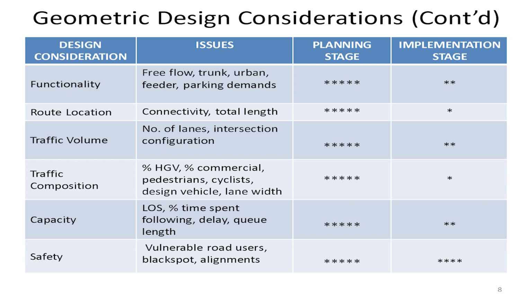Safety is the next. For safety, we are looking at vulnerable road users. We are looking at black spot elimination. We are looking at alignments. Can we safely go over hills? I mean, our crest curves. Can we safely go around objects, our horizontal curves? And they become pertinent issues, not only at the planning stage, but also during the implementation stage.